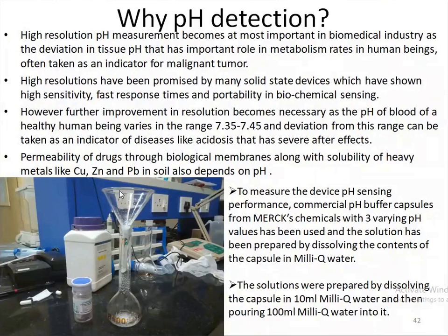So pH level detection can be used in various kinds of detections. Similarly, in the food industry or the heavy metal industry, pH detection plays a very important role. So pH detection is most essential, and developing a sensor that can operate in a rugged atmosphere is also important. For example, if we have to detect the quality of a concrete wall or a concrete brick, we have to go for a sensor. In that case, we can't use a silicon-based sensor because concrete has a basic pH.